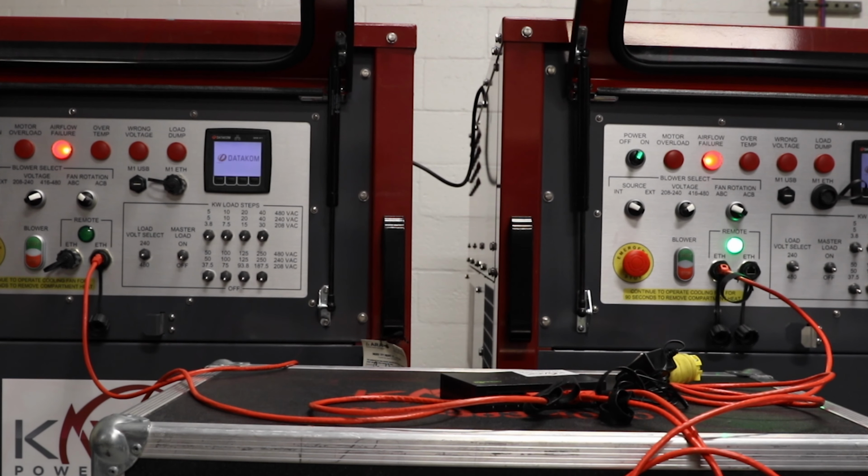Let's begin writing a script. Again, this script will be with us only using one group. There's typically a step called Step 001 already existing. First, you want to highlight this step. Next, on the right side of the page, you'll make sure your group is also highlighted, and then click on Pick Load. From here, you can select from a range of kW presets, which are in percentages of the design max we set up for our group.